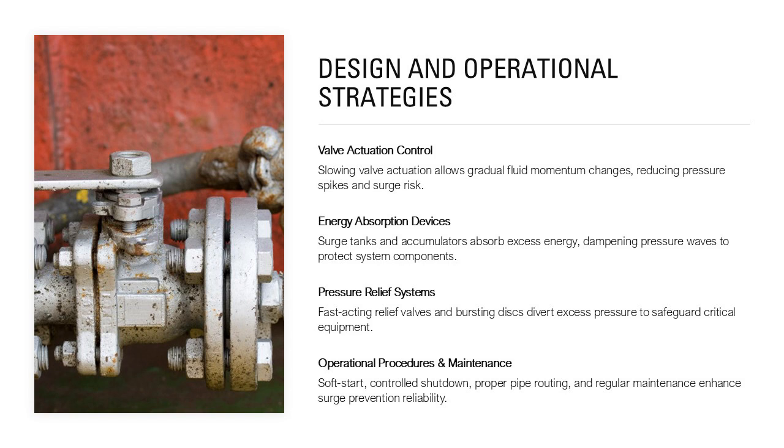Pressure relief systems, such as fast-acting relief valves or bursting discs, provide additional protection by diverting excess pressure away from critical components. For pump systems, implementing soft start and controlled shutdown procedures minimizes sudden changes in flow velocity. Pipe routing should avoid long unsupported spans and incorporate adequate guides and anchors to withstand transient forces. Computational surge analysis during design helps predict potential surge scenarios and optimize mitigation measures.